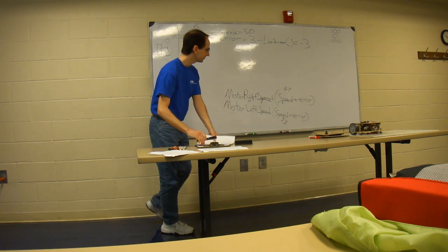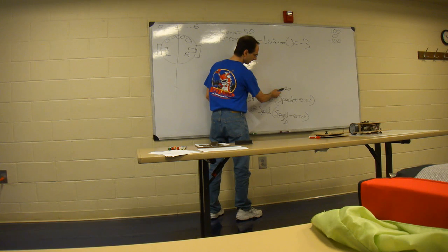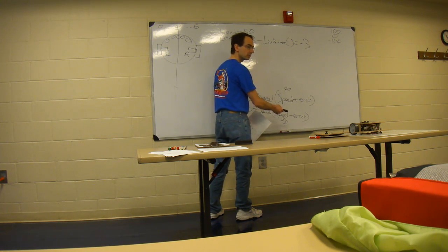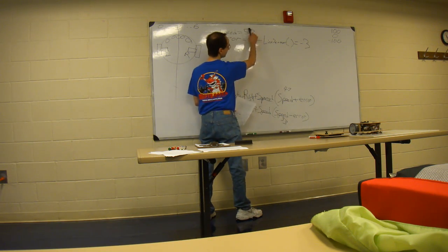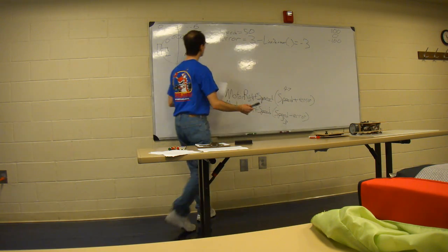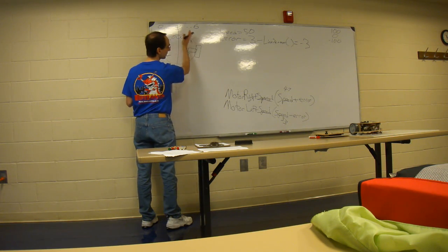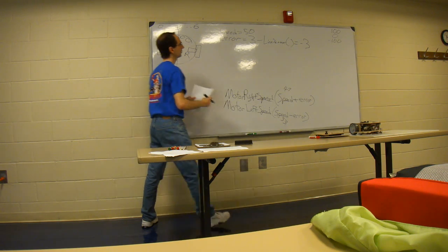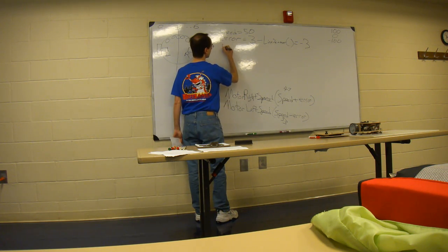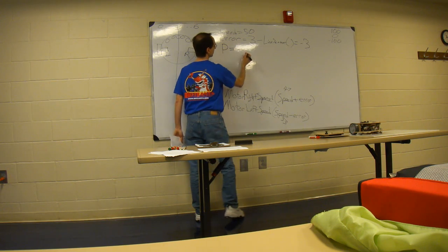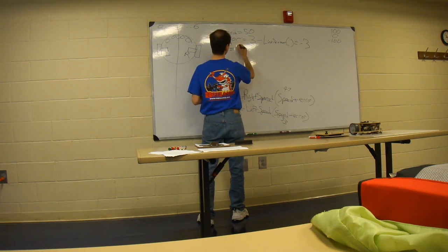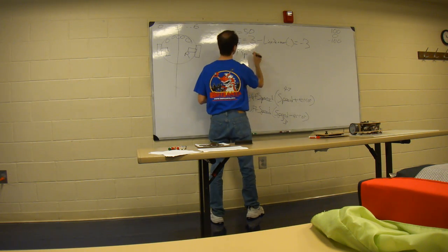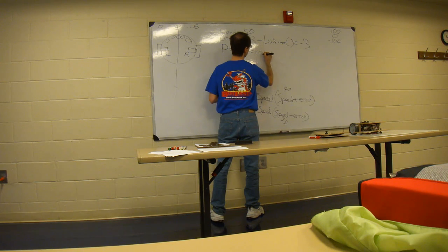But if you think about it, that's a very small difference between them. The speed of 50 versus the speed of 53, that's very small. And 6 is our maximum value. So we probably want to turn it a little harder. So what we actually want to do is have a constant called P, and we multiply that times the error.